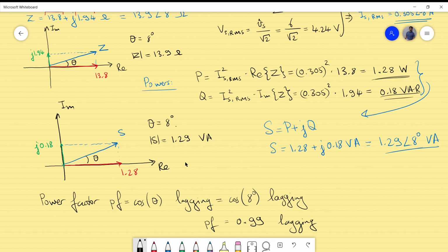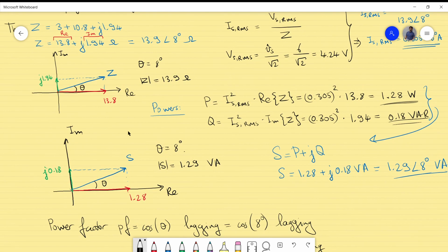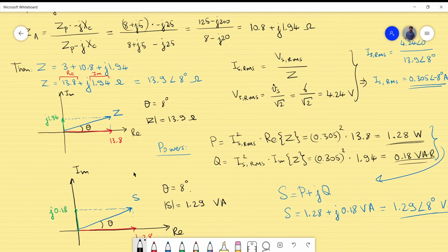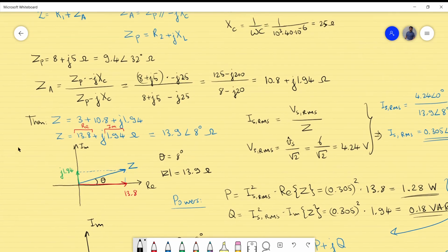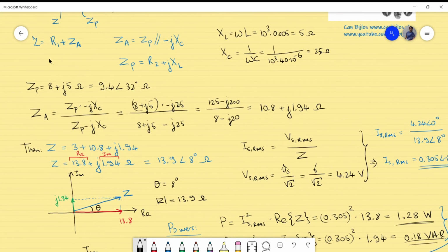So that's actually the whole procedure for this example number 5. We have dealt with the RLC circuit, a little bit more complicated than the other 4 examples, but this procedure is again exactly the same. You start from the total impedance, then go to the total supply voltage, and using the imaginary and the real parts of the total impedance and also the current, you can calculate the real and the reactive powers, and of course go from there to the apparent power and the power factor. I hope this will illustrate the concept again in more detail with a little bit challenging example.